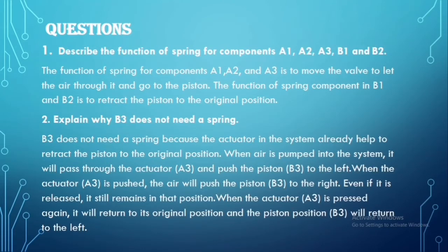Let's go to the question. Number 1, describe the function of spring for components A1, A2, A3, B1 and B2. The function of spring for component A1, A2 and A3 is to move the valve to let the air through it and go to the position. The function of spring component in B1 and B2 is to retract the piston to the original position. Question number 2. Explain why B3 does not need a spring.